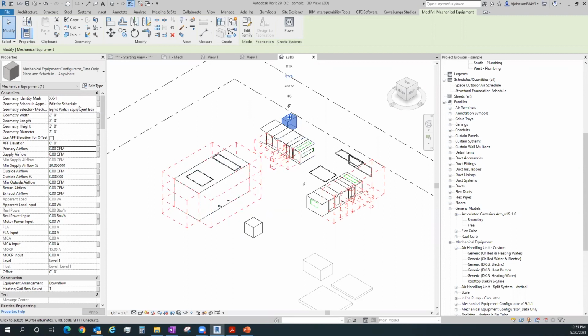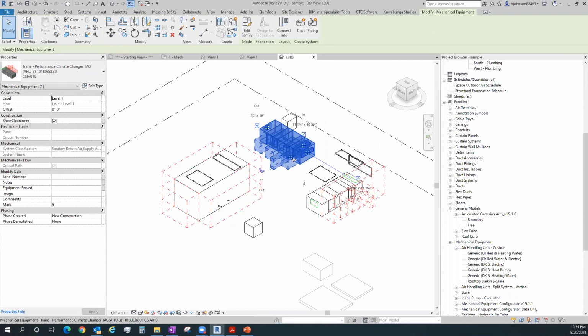So if I filled out that value as AHU, and the top one being AHU-1 or something like that as its mark number, then I could place this object in my model and schedule that object instead of this one, which I would not tell what my schedule appears on. I would just place my placeholder data tool directly in it somewhere and kind of hide it in there. And then I'd be able to see it in my schedule.